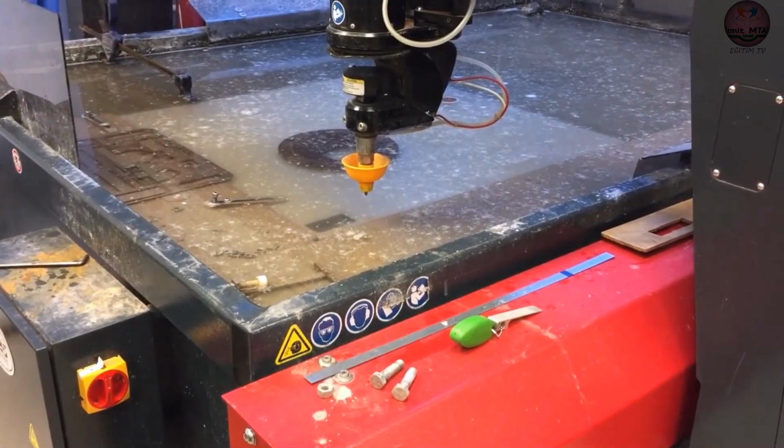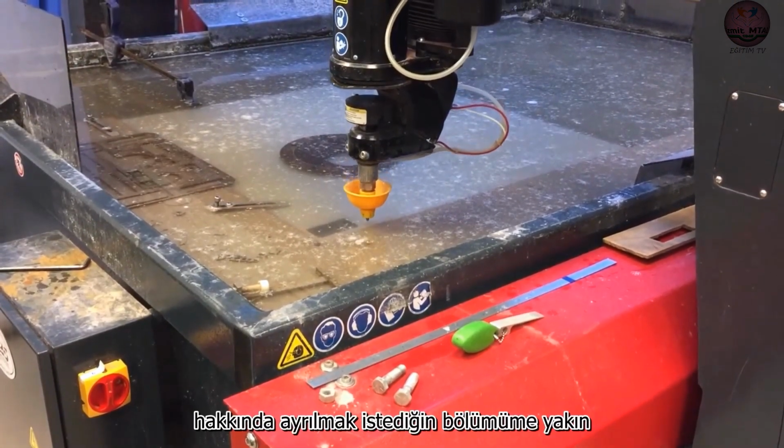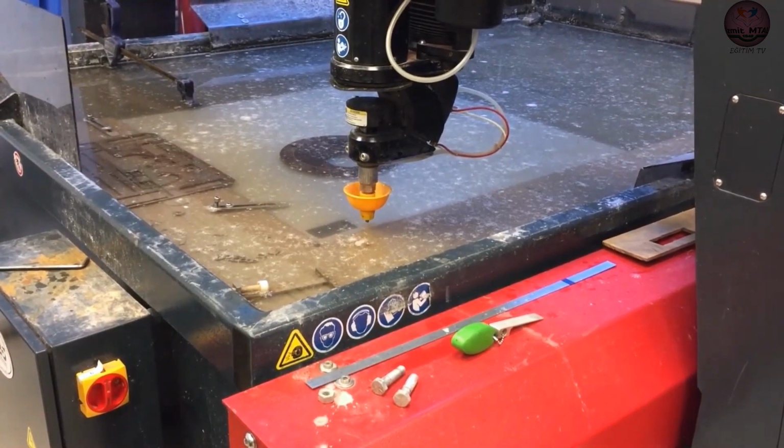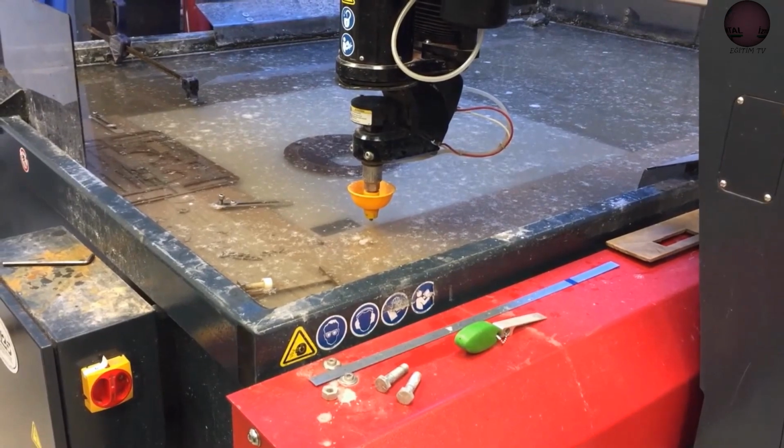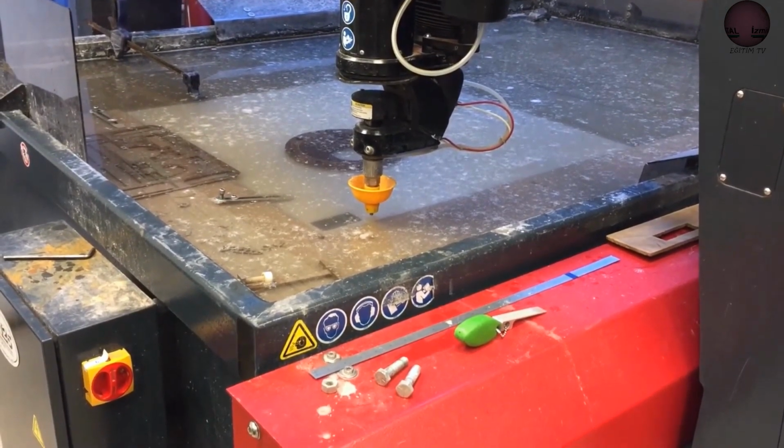So I'll use the 1 key to bring the nozzle close to my part. You want to leave about half an inch of space though. Don't get it too close at first.